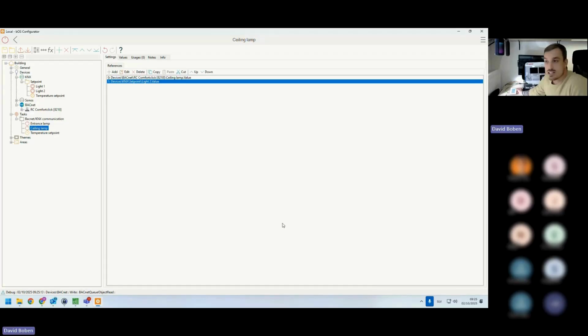And now with just a simple variable, an entrance lamp Boolean variable, I was able to very quickly and easily have this communication between KNX and BACnet. In the past, in some cases, when it comes to some specific statuses and control, you will still need to use, let's say, a program task for checking up the statuses. But in most cases, with a simple integration like this, you can just add a variable and add these two in, and it basically communicates both ways.